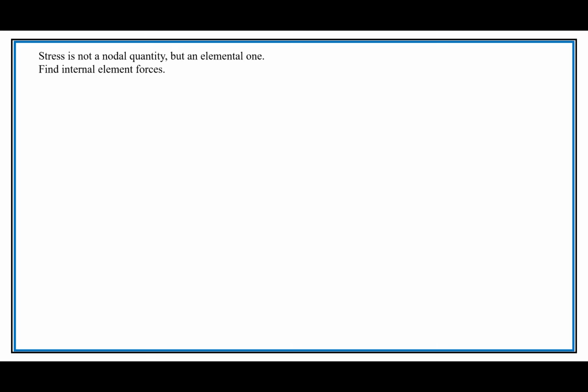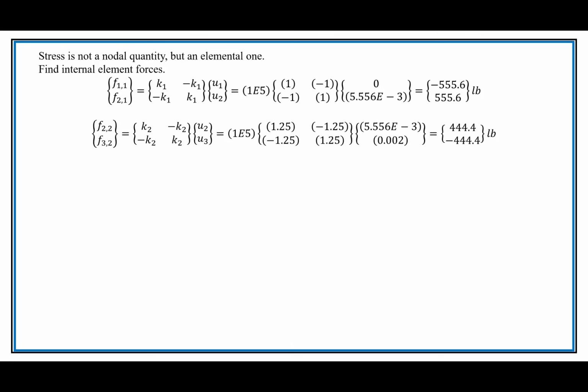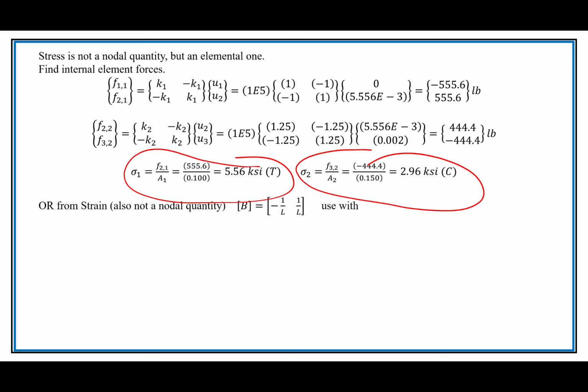So now we go for the stresses. Notably, stress is not a nodal quality; it's an element quality. So we can place them in here and find what the stresses are going to be. Not hard to do. And the strains are also not a nodal quality.